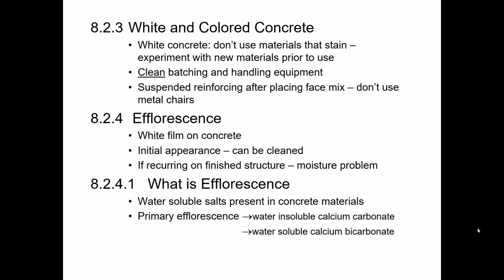So you've got white concrete with little gray dots spaced at some spacing once you etch it. That wouldn't be great. So obviously, suspending the reinforcement is best, and certainly don't use metal chairs that can then rust and stain the surface as well.